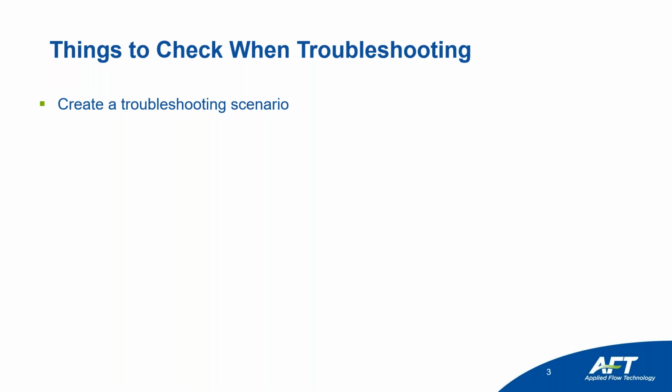I'm always going to create a child scenario of that, and after I create that child scenario, I can change whatever I want in the child scenario, and then I can always go back and reload the original scenario and preserve the original issue as it was in its original state. So you're going to see what that looks like today. Whenever you're doing your troubleshooting, do it in a child scenario, not the main scenario that you're actually having the problem in.